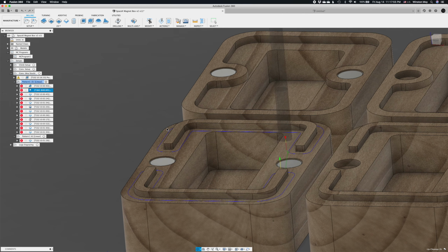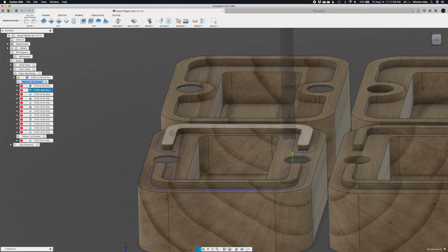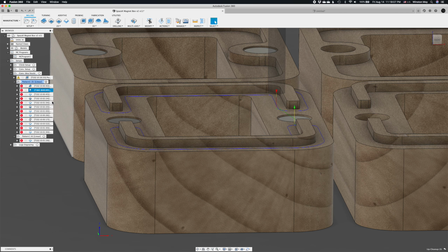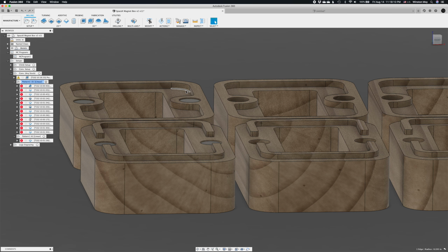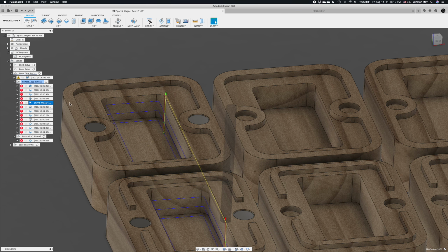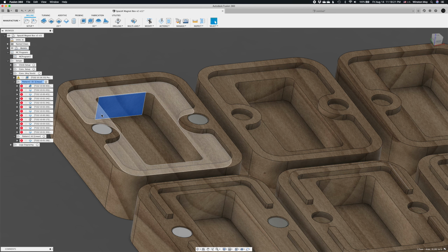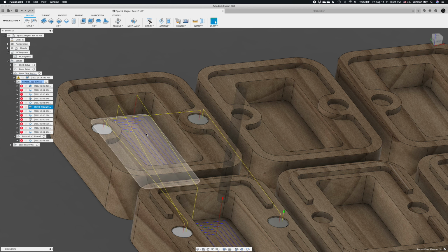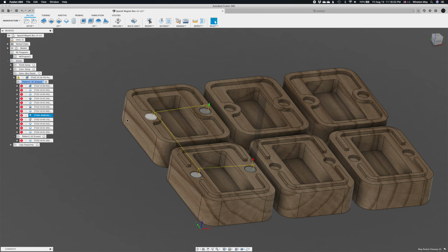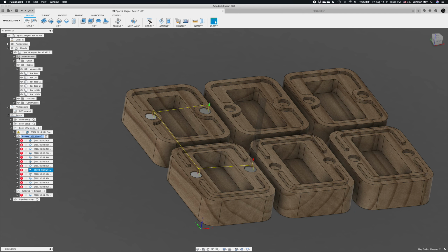After the trace, I clean up the inside walls, leaving a little bit of axial stock to leave so this toolpath doesn't completely touch the floor. It's hovering just 1.5 thou above that surface. We'll clean up the inner ledge here, just the outside perimeter. Then we'll hit the faces, pocketing toolpath, clean up the inner walls here, do a pocketing toolpath to clean up the floor, then a full depth of cut spring pass, and also just to erase any waterline marks. These are the cleanup toolpaths for the magnet pocket.